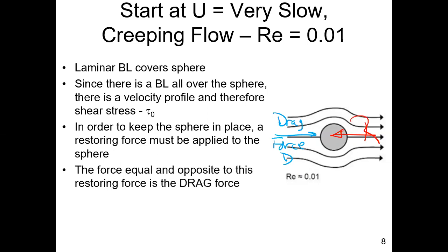If you did not have the restoring force, at this instant the drag force would start pushing the particle in the direction of the flow. And as that particle starts moving, again, it's relative motion. You would have a velocity of the particle and a velocity of the fluid, and the difference between those two is the relative velocity. Ultimately, if the particle moves at the fluid velocity, there's no more drag force. The system's in equilibrium. This is the same concept we will use in designing some of the first components of wastewater treatment.